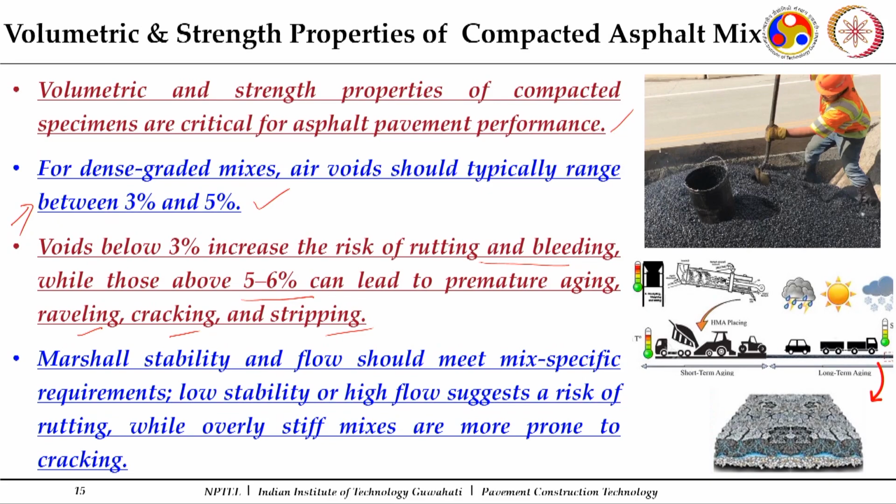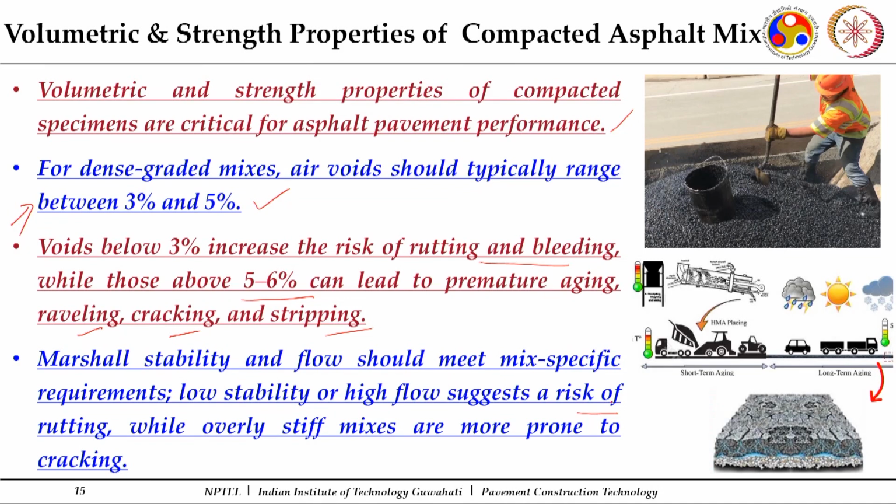So, that particular mix should meet those requirements, and specifically we need to look into it, because a very low stability and high flow may indicate a mix which is prone to rutting, because that shows the mix is soft enough, while an over-stiff mix may also be prone to cracking. A mix which is very stiff may crack when it gets deflected under the traffic load.